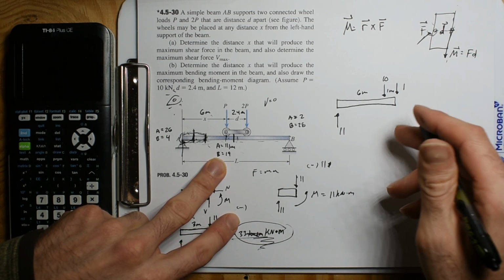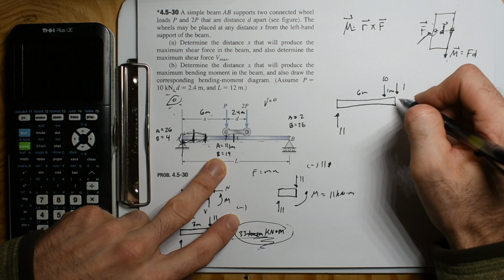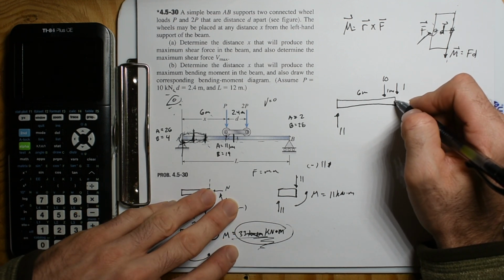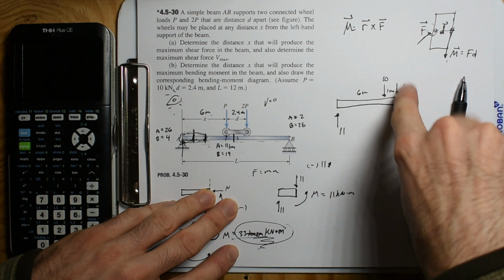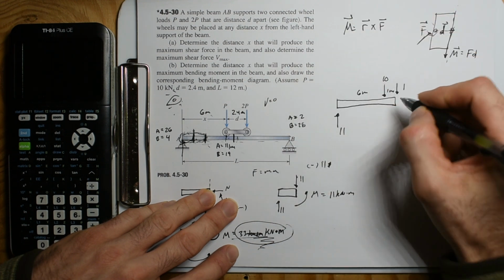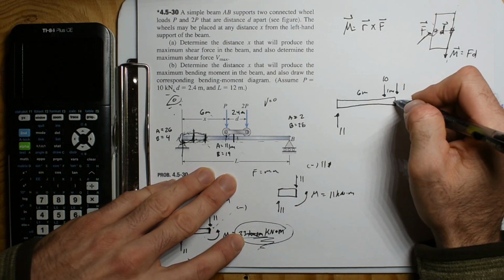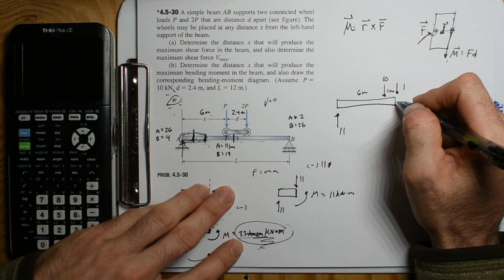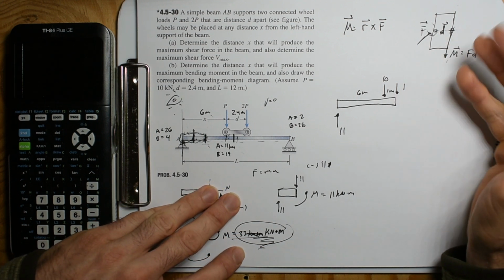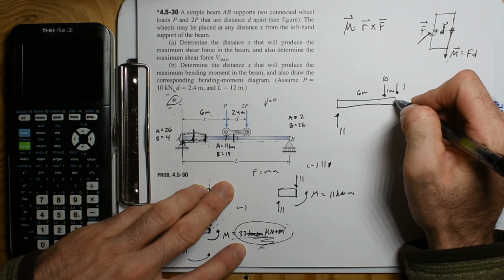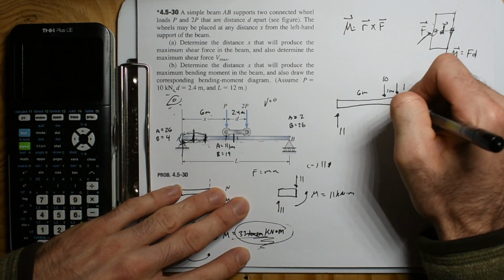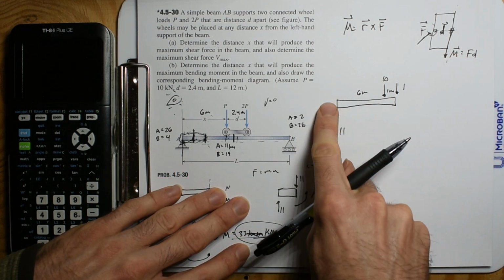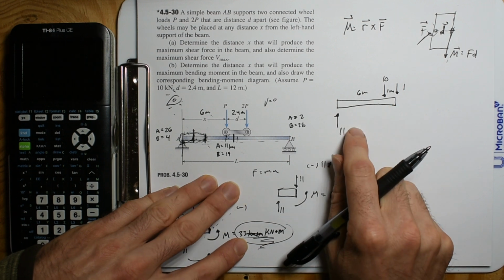And now let's see if our moments are balanced. Well, obviously not. We have 11 kilonewtons this way and 10 and 1 going that way. So we have negative moments. So we're going to sum the moments. Where should we do this? It doesn't matter. Like, the only place that you can actually put a moment is right here. But like I said, you can sum the moments anywhere.